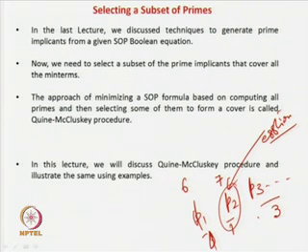But for other cases, for example, if P1 has 4 min terms, 1 is in P2 and 3 are in P3, you can drop P1 and take P2 and P3. The essential prime implicants are those which have a min term which is nowhere else available. That is to be included, but some other prime implicants may be such that their min terms are available in prime implicant A and in prime implicant B. So you can totally throw away this first prime implicant and take the rest of the 2.